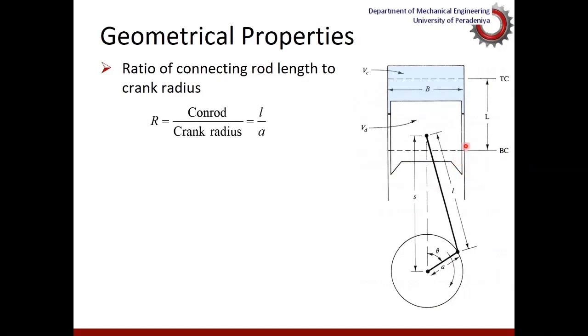So now this friction force is the force acting vertically up or down, as the piston moves up and down respectively. That vertical force comes due to the horizontal force applied onto the wall. So if the horizontal force is R, then mu R will create the frictional force. So if you can reduce the horizontal force, then mu R also will be reduced.